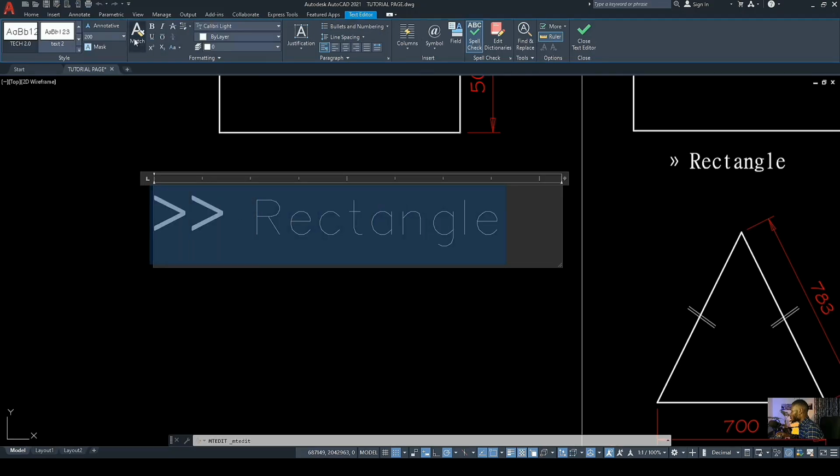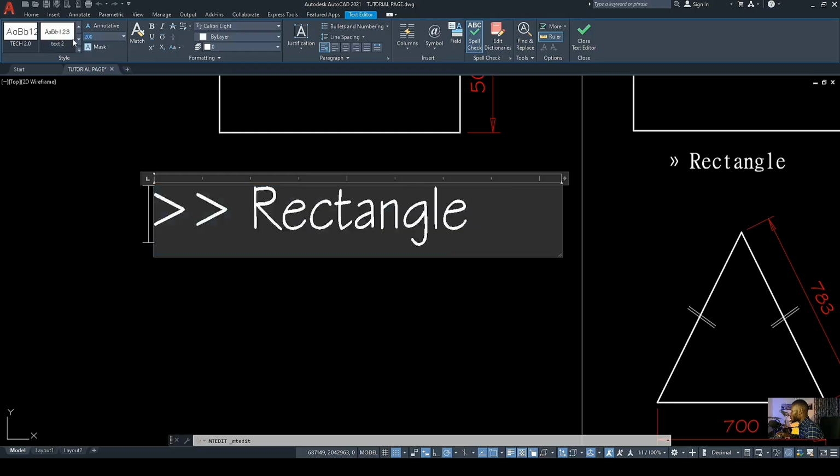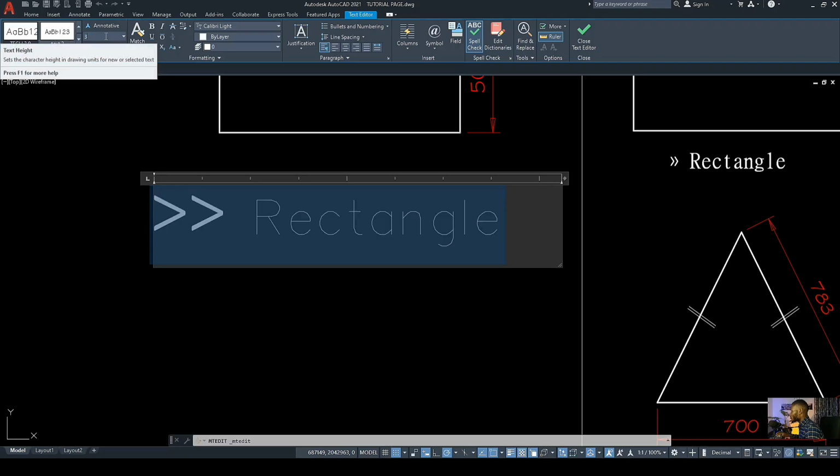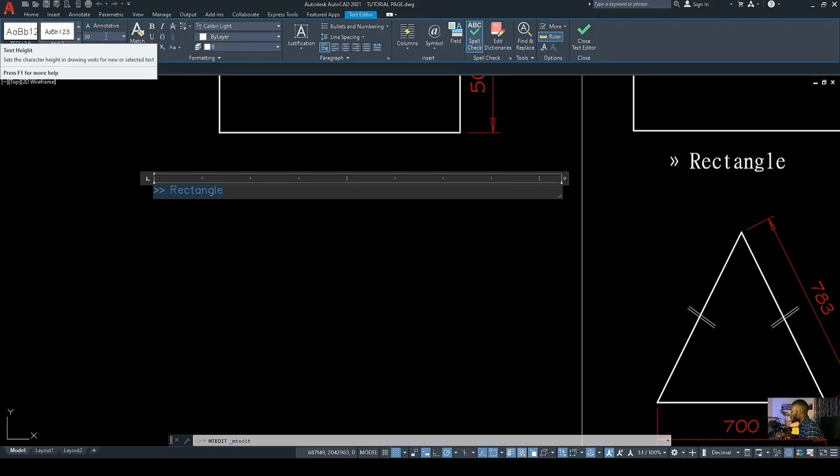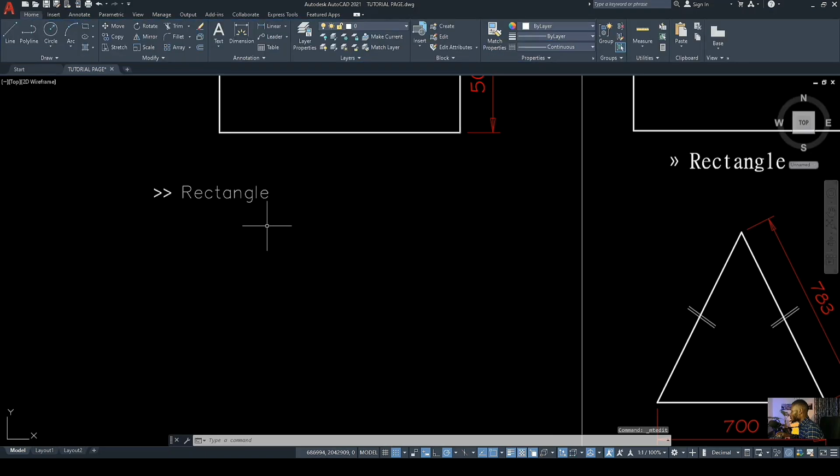So we'll start by this. We can drop the scale of our text to, let's say, 30. Let's see what it will give us. You highlight and you type in 30, then enter. 30 is way small, so we can increase it again. Let's say 50, enter. So this is kind of preferable.